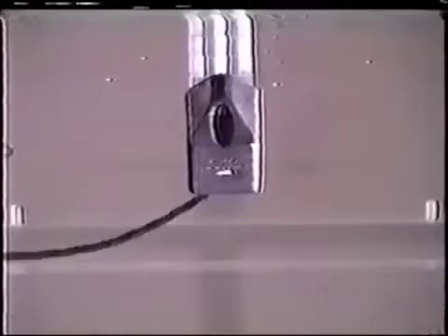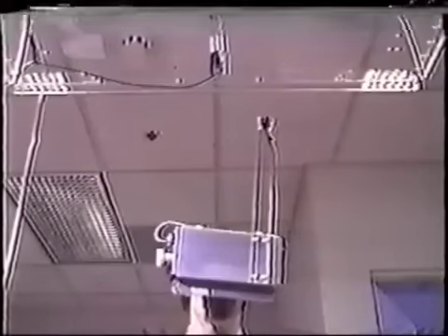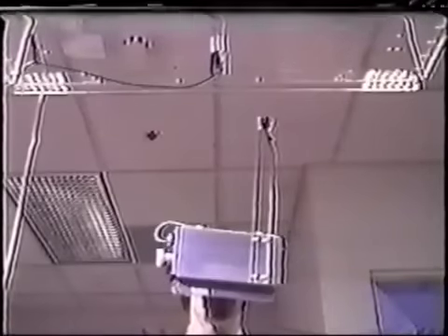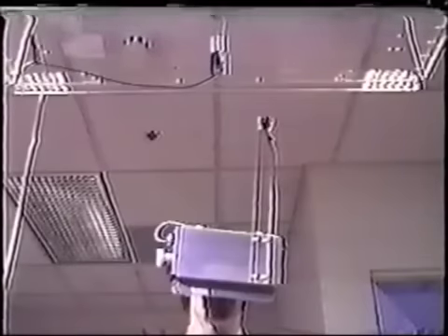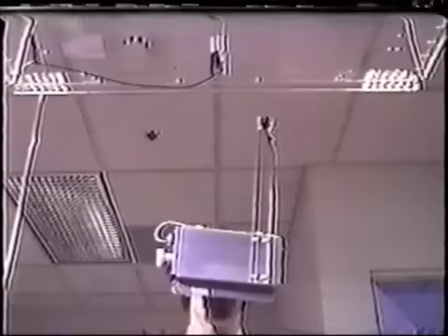Just a picture of a Polhemus tracking device. This is the source of the electromagnetic field generated by the tracker. This is the same 3-space tracker that was measured in the previous little video clip. This is a head mount of the NASA Ames View Lab, showing that same tracker source at the top of the screen, and mounted on the head mount on that transparent stalk is the receiver of that tracker. So this is how one would do head tracking with the head mount.